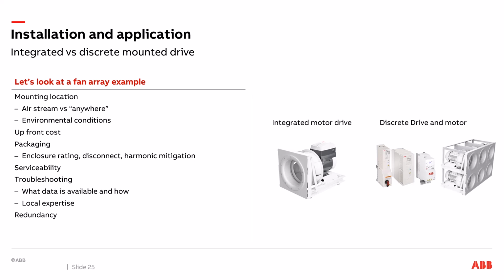You don't have to use another ABB drive. You can basically buy a different brand of drive and install it in there, and it's usually a pretty quick and easy integration. When you look at the integral motor drive solutions, that's where it's a little bit tougher to swap from different drive brands. In the case of the EC titanium, you'd essentially have to take that drive off of there, then find a different drive from a different manufacturer and find a spot to install that, move all the control wires. It's a pain. It's not easy to do.